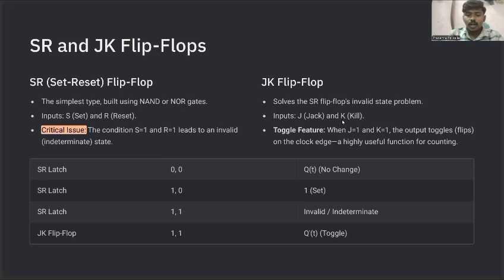So S 0 and R also 0, no change in condition. So previous state retained. So S 1 and R is 1, no change occurs. So it is considered as an invalid state. Because of the invalid conditions, the SR flip-flop is not widely used in practical circuits.